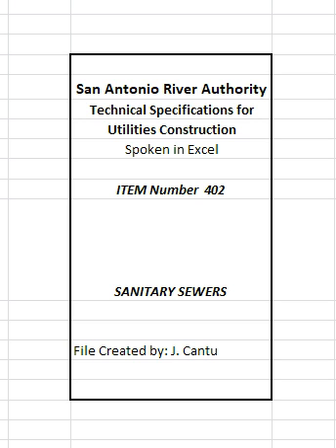6. Polyvinyl chloride (PVC) pressure pipe. PVC pressure pipe used for force mains or other use as specified in the plans shall conform to a minimum of SDR26 as specified in AWWA C900 and AWWA C905. It shall be hydrostatic tested at the lowest point to a pressure equal to 2 times the sum total of the pressure due to the design hydrostatic head of the water column plus the total friction loss, with a maximum of 150 psi.